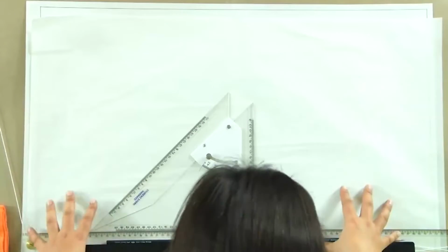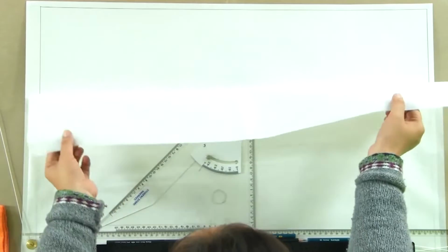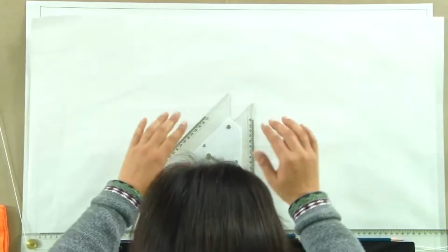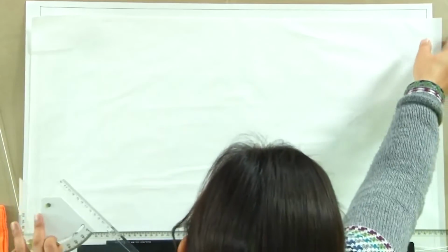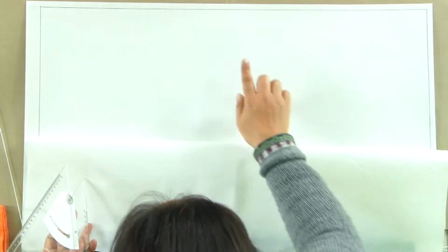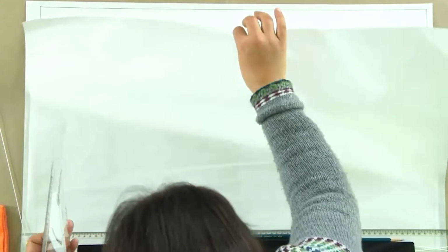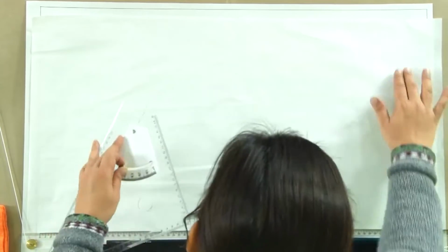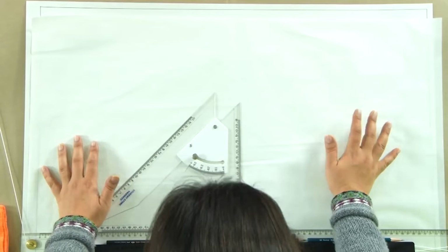So, we left this board yesterday in this manner, and if you notice, I covered the sheet with a butter paper, a butter sheet. You should always do this, you should make this a habit, because the butter sheet allows the line not to smudge. It helps it to stay intact and your sheet will not get dirty. So always you should cover it with a butter sheet. At least a set of these sheets you should keep.